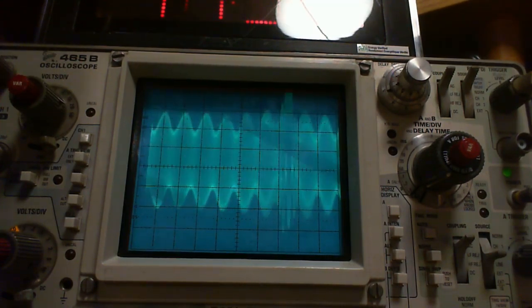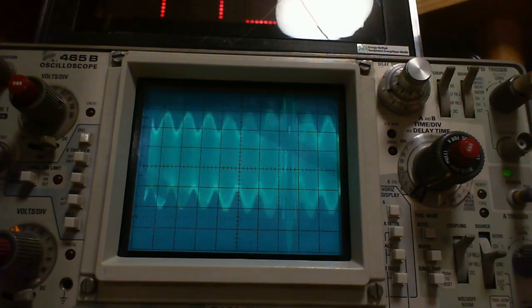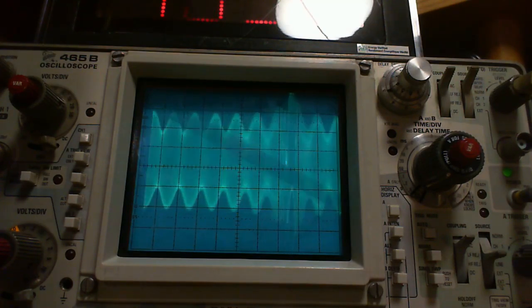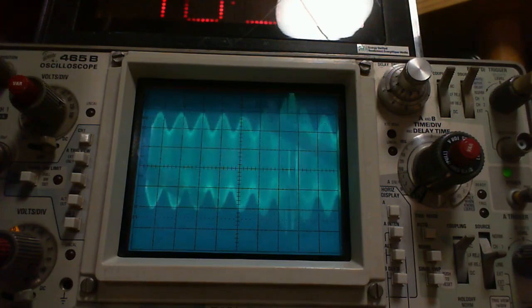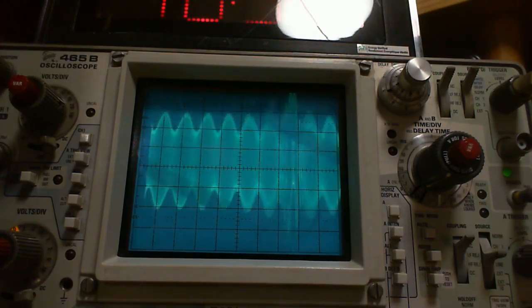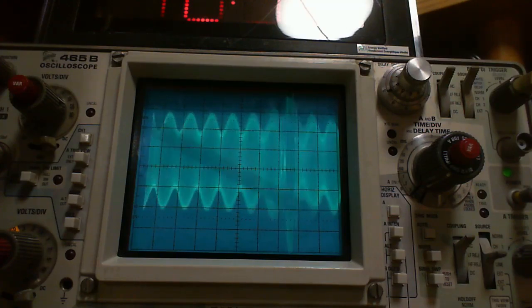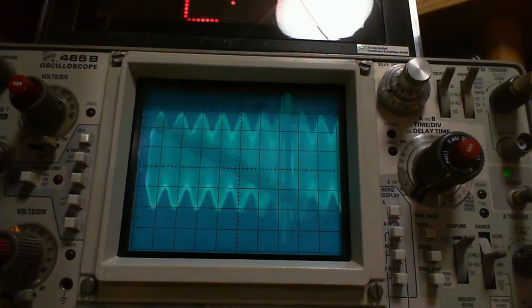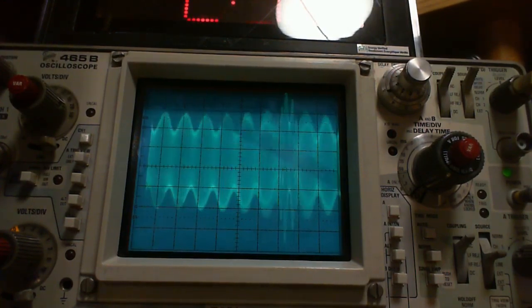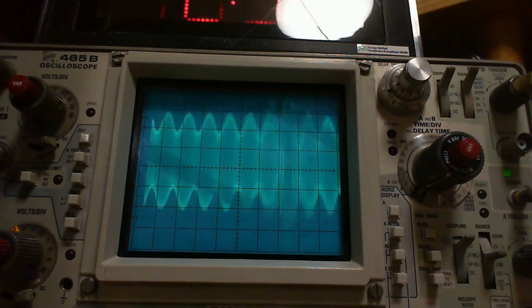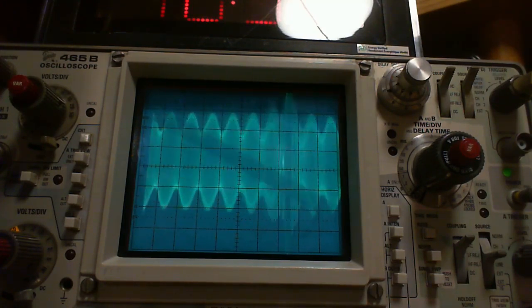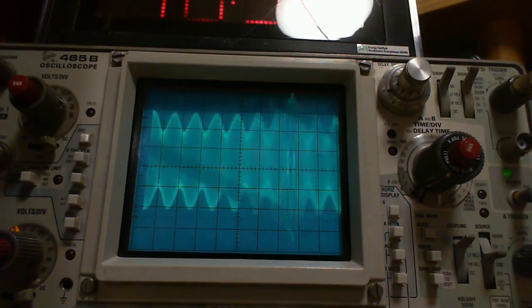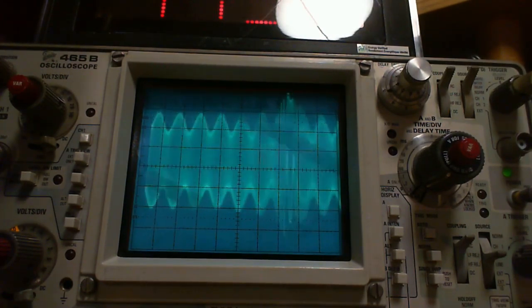And of course my frequency counter's gone nutso here again, so I can't see the actual frequency. So we'll just leave it like this for a second and think, what are we actually doing here? We're measuring the resonance of the whole front end of the radio. We're looking at it on the scope at the output. We were looking at it right at the point where the tuning capacitor meets the coil it's tuning against. We're right on that coil. I think that would cause a little bit of interference, but it doesn't seem to.